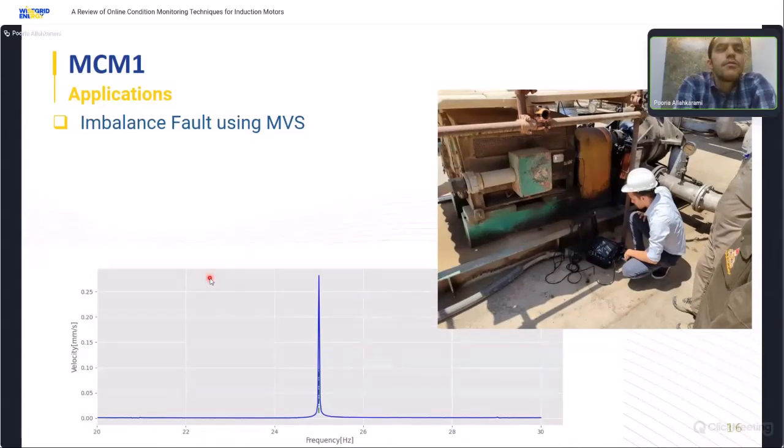As we talked about before, this condition can be observed in the vibration frequency spectrum. It is important to remember that this component is always present in the motor vibration spectrum, but the imbalance causes its amplitude to increase significantly. Therefore, to detect this fault, we need to compare the current test result with the historical data and periodic tests of the electric motor to detect the mass imbalance in the motor.